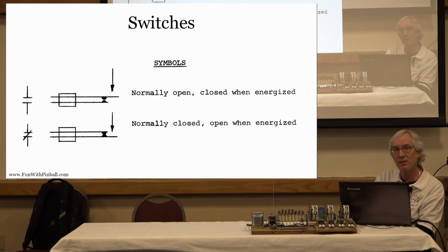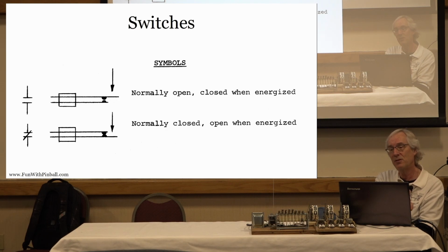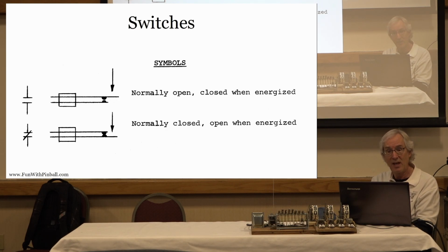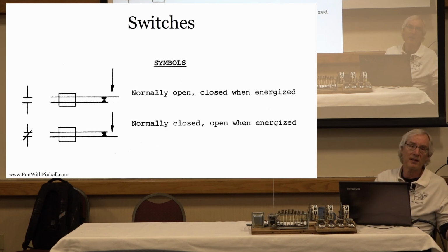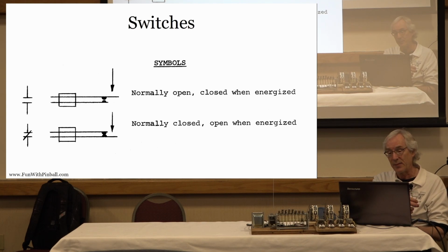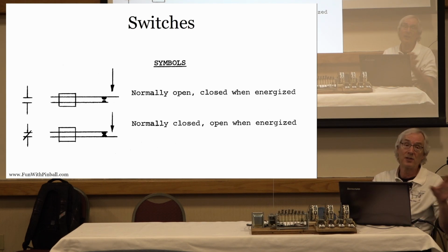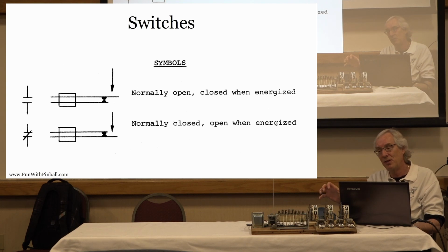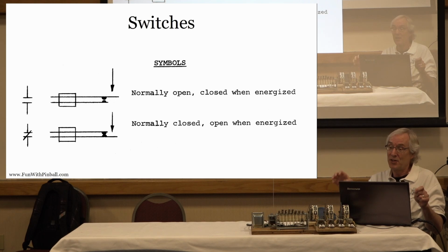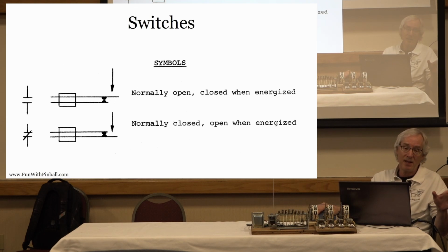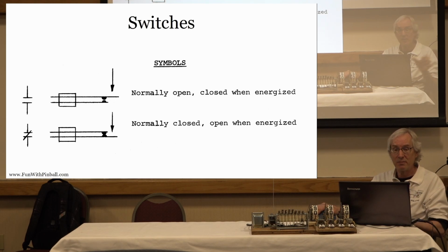And now I can control the current that's going to go through that coil. Most of these devices that use coils are going to use the magnetic field to pull something in one direction. But it's going to be a spring that actually pulls that device back to reset it in the other direction. So the magnetic field only works one way, and then I rely on a spring. As that magnetic field pulls a plunger or a relay or something, it's actually stretching out a spring and putting energy in that spring. So when I cut power to that coil, that spring is what's going to pull it back to its steady or reset position.